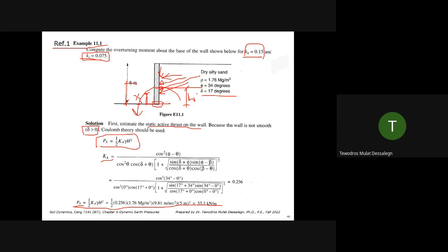The main difference is just getting the seismic forces and then combining them with the static, then the design remains the same. The amount of reinforcement you need for a static force only is much less than when you combine the dynamic force. This is the simplest approach. You can do this by hand. You can implement these equations in Excel or preferably in MathCAD, and automatically you can get the solution pretty fast.